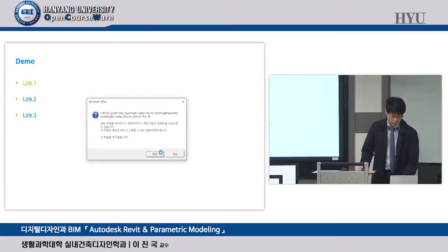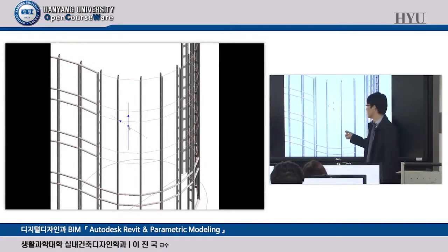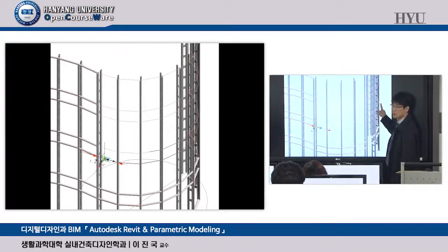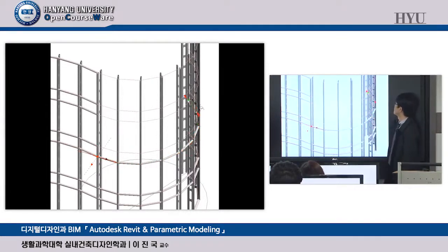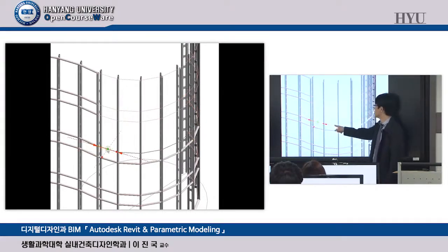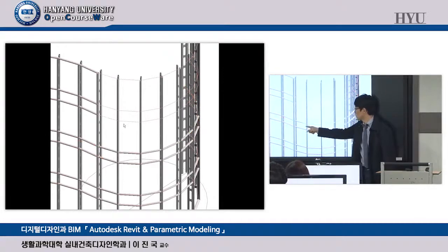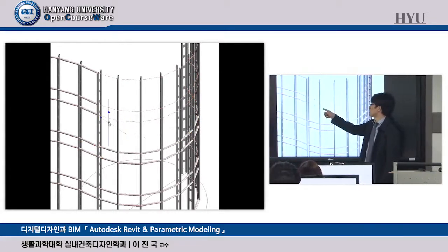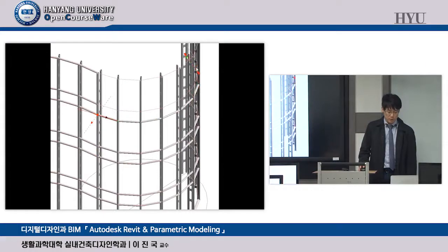Okay, the next example will show you its physical installation, the horizontal mullion. So all the path data is defined, and this is a solid object. So click the path and starting point and simply follow the path line, and then this one is automatically cut by the equation that I showed you in the slide, and all the horizontal bars are going to be installed in this way. Okay, this is a sort of parametric approach to define this structure. Take a look, the angle cuts are well formed and installed based upon the user input for this one. So installed and measured, okay, until the end point.